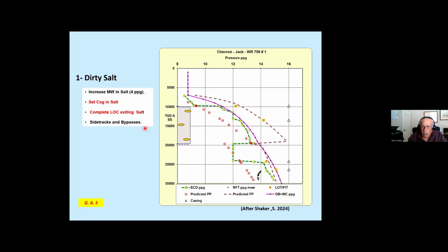So what happened here? Why did I say in the model the salt doesn't have fluid, it doesn't have permeability, so the pore pressure is supposed not to change? But if you have embedded sediments in the salt, every time the drill bit hits those sediments embedded in the salt, it hits some pressure, and the tool pusher cannot respond to this, so increases the mud weight.